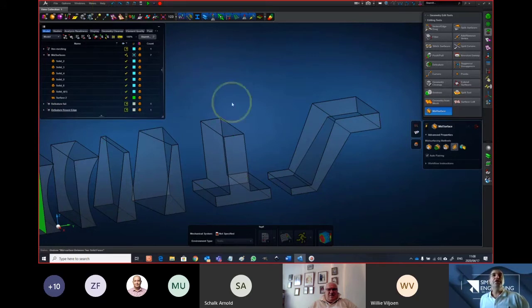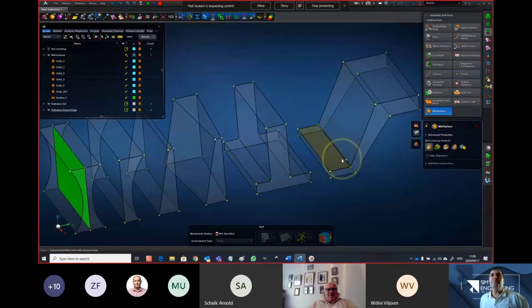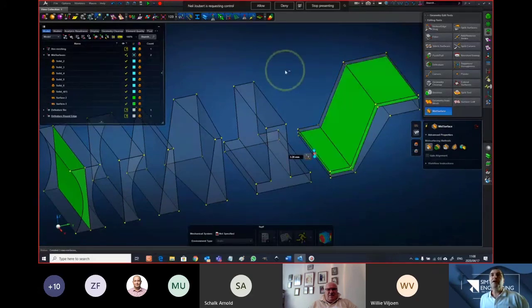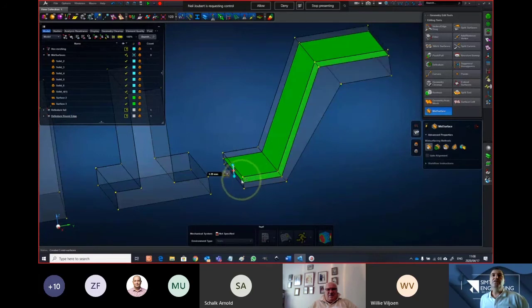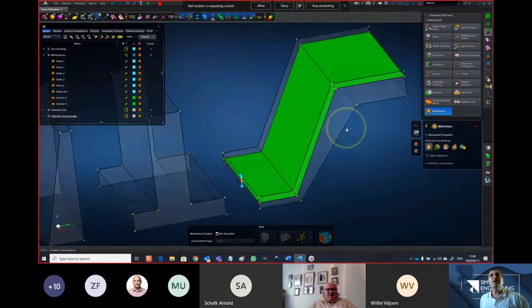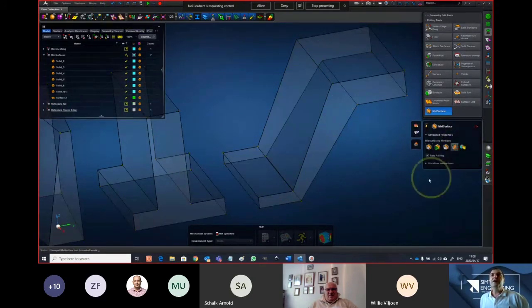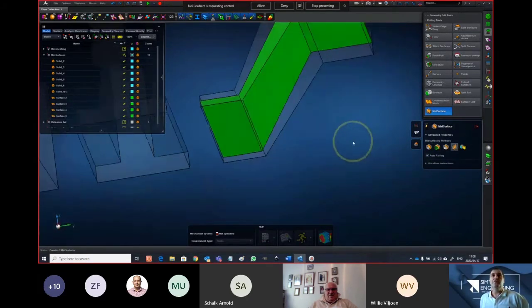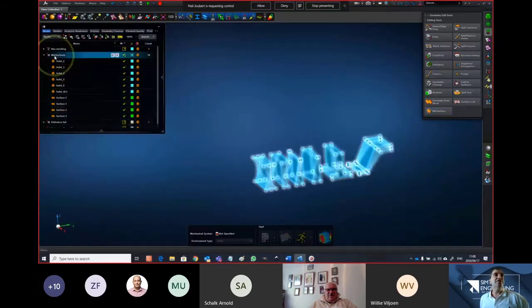If we don't do this and we use the manual method, it may or may not work. And as you can see, it then also only uses the first section to dictate or determine where the mid-surface would be. So for varying thickness structures, this is the better tool to use. All right, so I thought I'll just draw your attention to those.